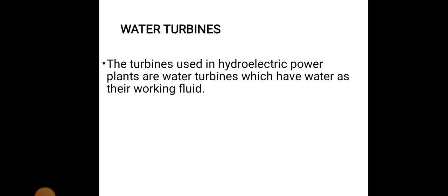Example: Pelton turbine. In the reaction turbine, the turbine blades or impeller blades are designed in such a way that a force is generated on one side when water flows through it, just like an airfoil. The force produced by an airfoil is responsible for the lift of an aeroplane. Similarly, here the force makes the blade rotate. Example: Kaplan turbine. So different types of turbines have their own ideal operating conditions.